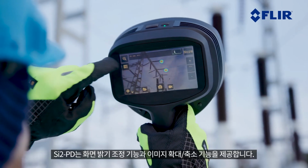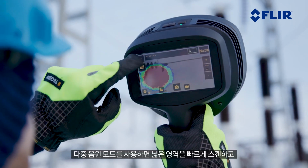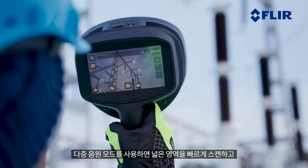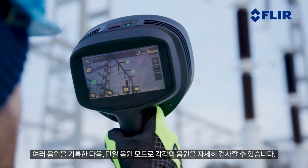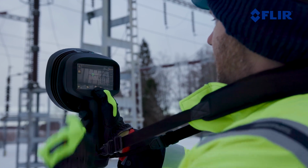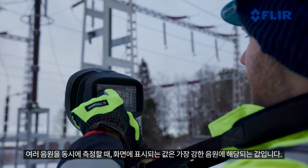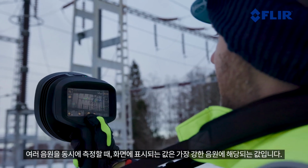You can adjust screen brightness and zoom in and out with the camera. You can use the multi-source mode to scan a large area quickly and take note of several sound sources, which you can then inspect more closely with single-source mode. Note that when visualizing multiple sources, the camera will only analyze the strongest sound source indicated on the screen.